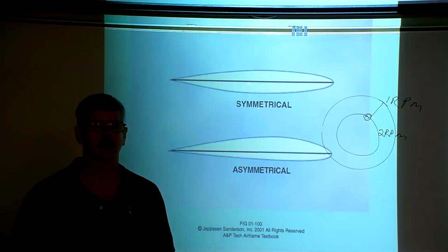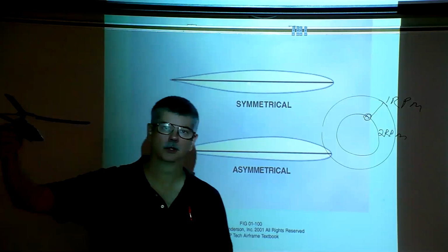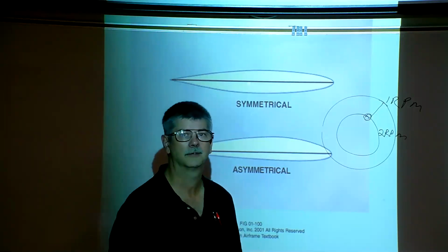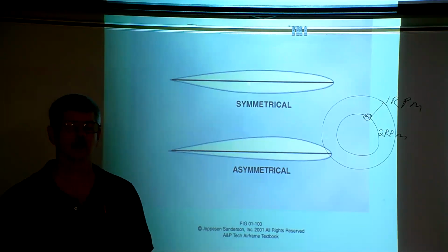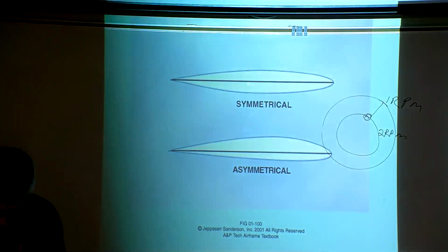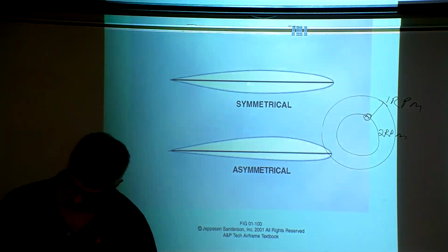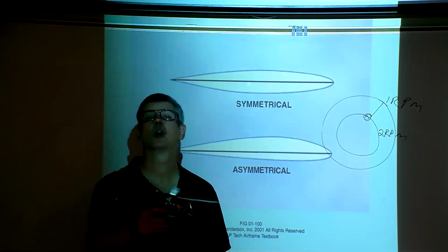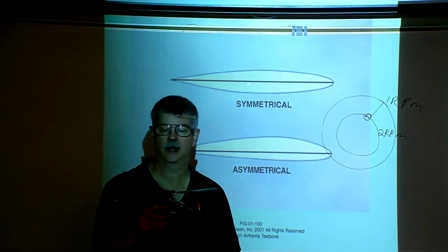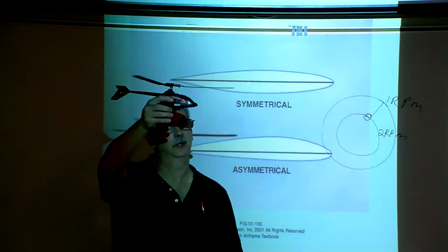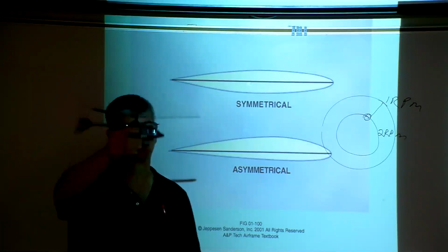When we want to come into land, we descend almost like a regular fixed wing aircraft. Now, when we come into ground effect, this is when we can hover and maneuver normally. The vertical ascent and descent: if we push more air down, meaning the weight of the air down more than the aircraft weighs, we go up. If we reduce the amount of lift, we come down.